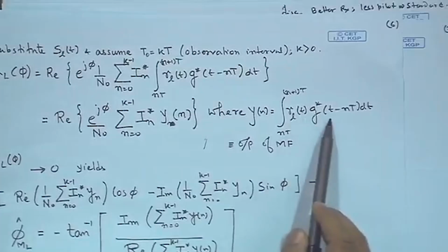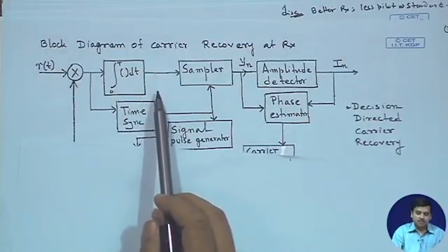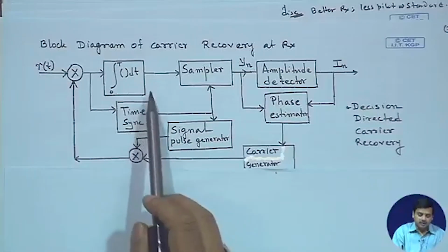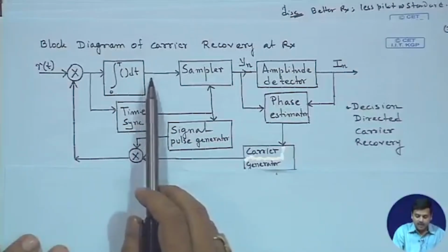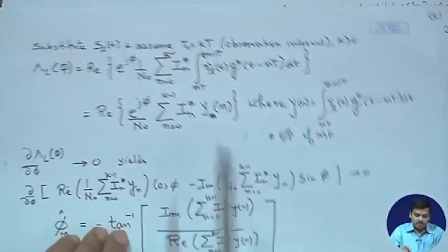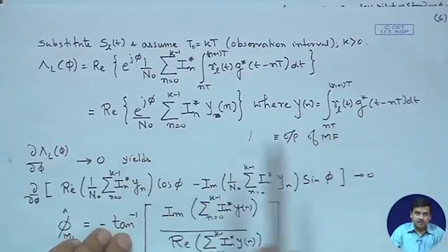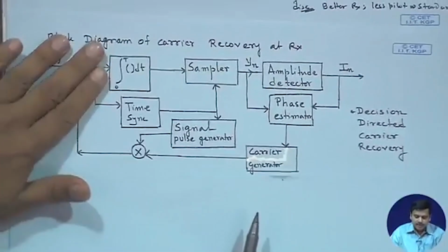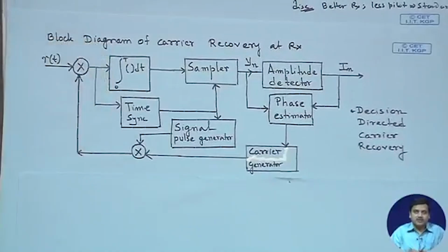The pulse generator is g(t), and once it passes through this filter or this integrator, you are left with the residual phase, and the expressions finally yielding to this have been translated to a block diagrammatic representation which is realizable. So, we stop the discussion on carrier recovery at this point, and just try to summarize. We started with the philosophy of estimating signal parameters.